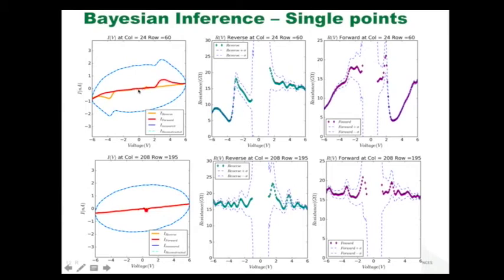Note that we're not able to see the switching currents in the standard IV measurement. We're only able to see them in this general mode IV measurement. And the reason is quite simple. Remember I said that there was a delay time in the standard IV measurement. That delay time is typically on the order of a few hundred microseconds or a few milliseconds or even a millisecond. And that really means that if there are these kind of dynamic phenomena occurring on the millisecond timescale,